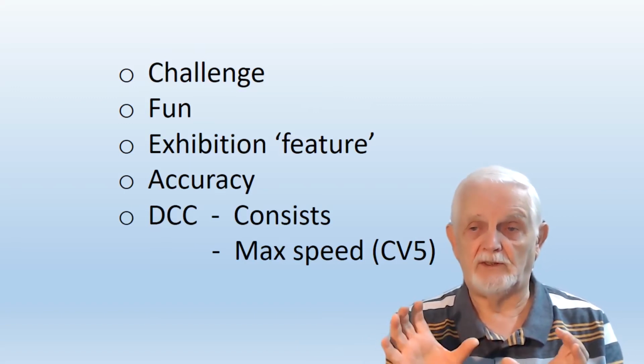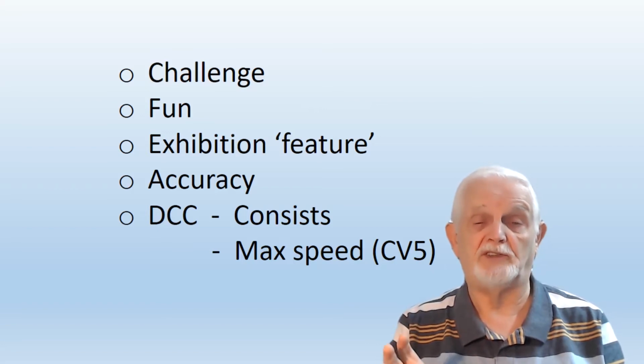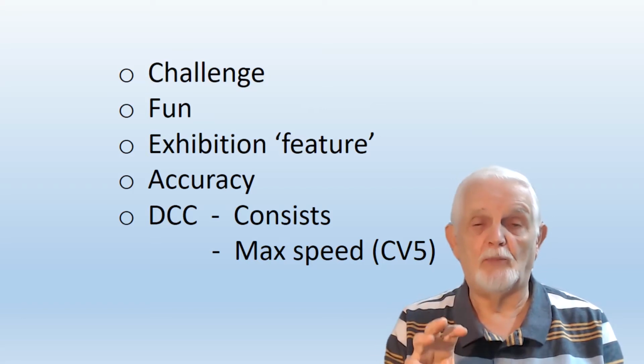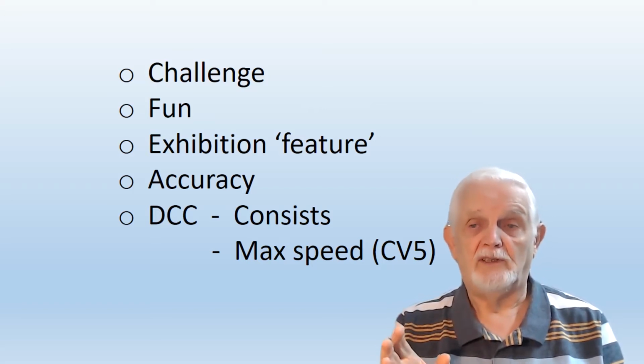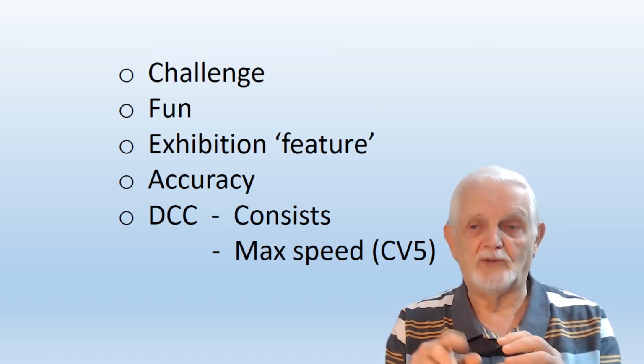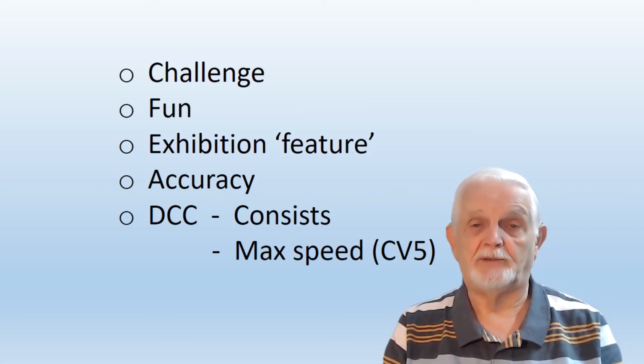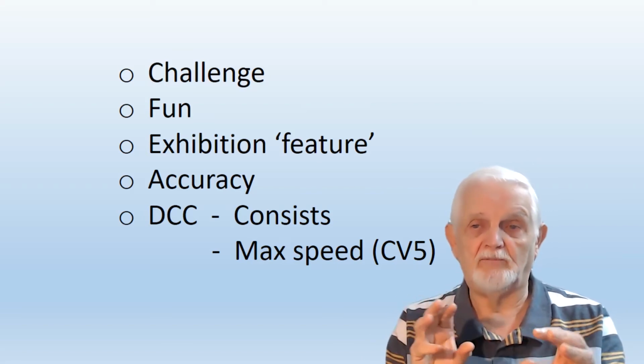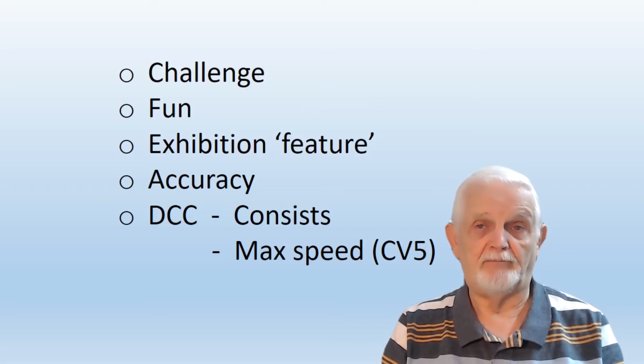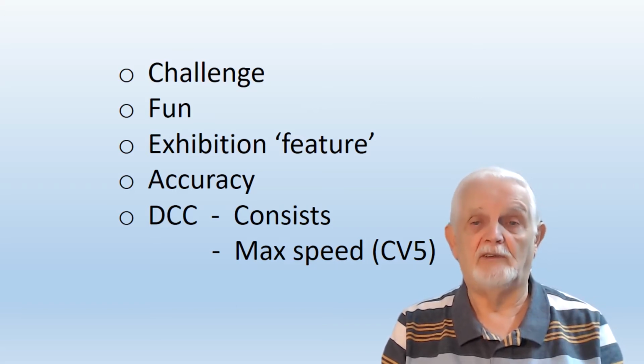And you have to set those two locomotive speeds to accord with each other. When you set the knob to 1/3 speed, they should both go at the same speed. Otherwise, one wheel's going faster than the other and the wheels slip in one of the locomotives. So you have to tweak them to both respond exactly the same. And this will be very helpful in doing that.